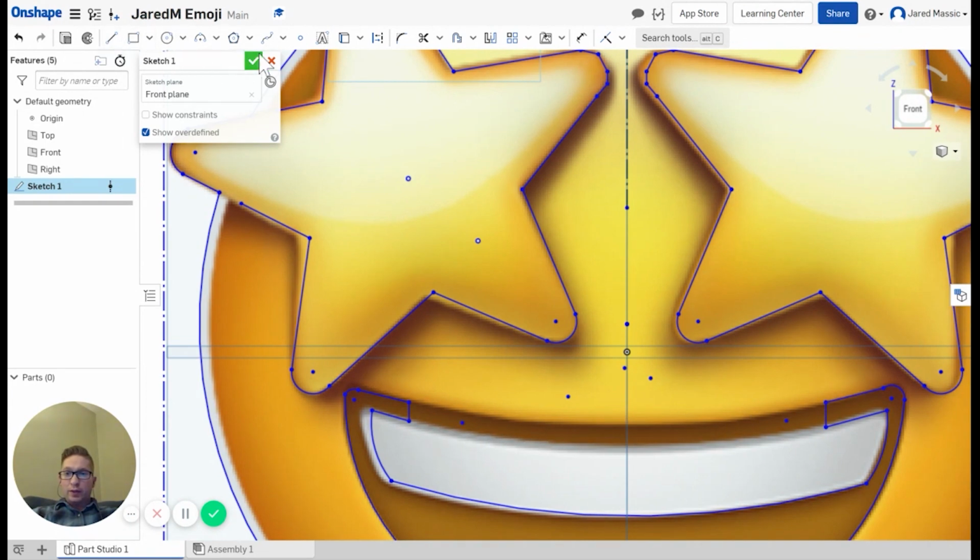So I'm going to throw in another silhouette cut. I call them silhouette cuts because essentially they're not going to drop out. The plasma cutter is going to do a single line cut, and it'll just try and maintain that shape of teeth, give you the appearance.